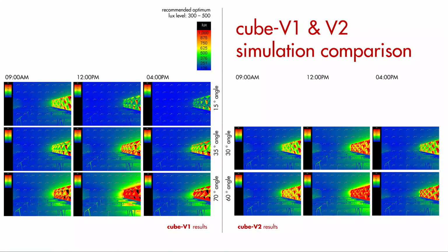With these design explorations and the objective of identifying the effectiveness of this external facade, I have simulated these two iterations using VLux Daylight Visualizer to test the solar radiation. We can see from these results that it is not up to the optimized level of 300 to 500 lux. Hence, further design exploration should be tested to get the best out of this exploration.